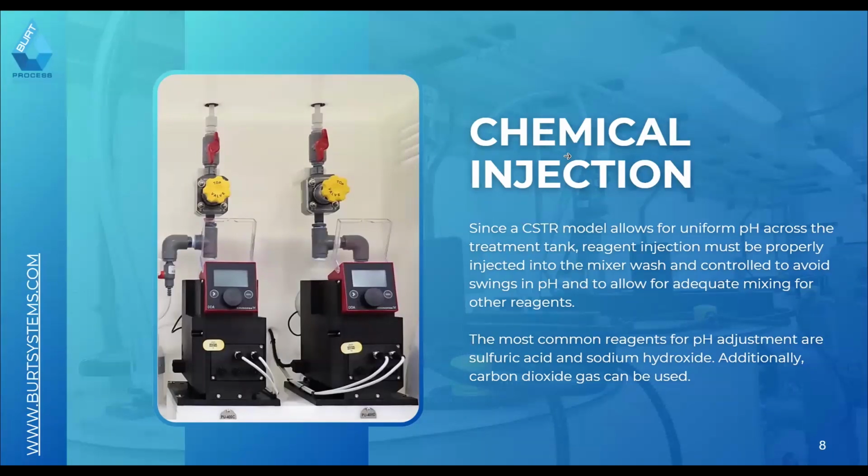All right, and it looks like just about everyone got that right. It is both the pH of the waste and the flow rate. So as Mark was saying, depending on how many units of pH you need to move your waste to be an acceptable discharge, that definitely impacts how long you need to have the waste in the system to make sure it can move to within an acceptable limit, as well as the flow rate, depending on what kind of incoming flow you have and how large the tank needs to be to do that residence time.